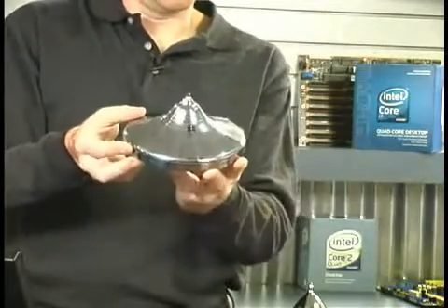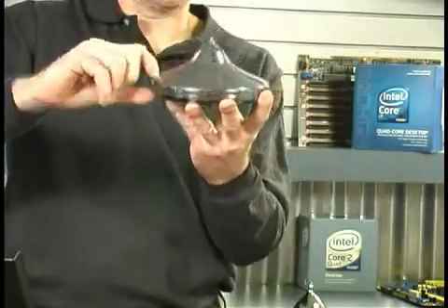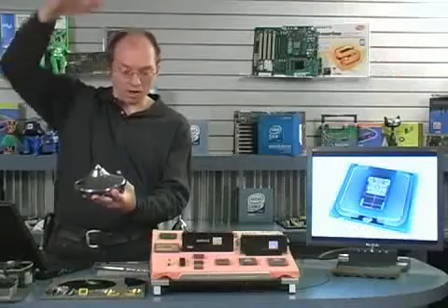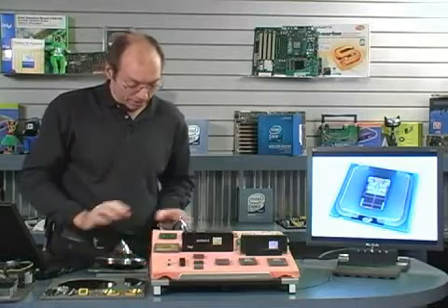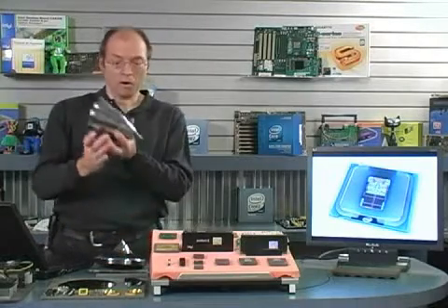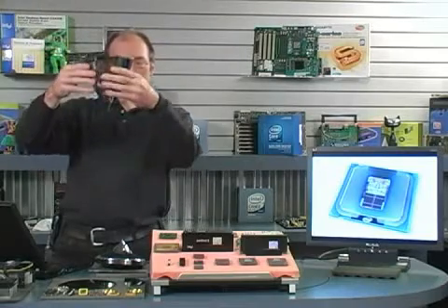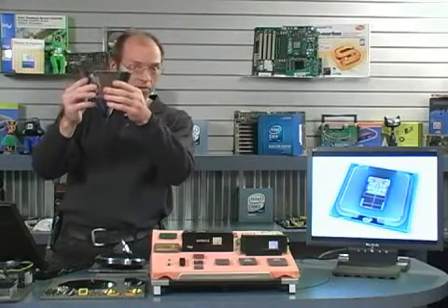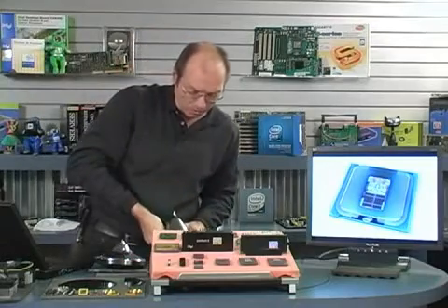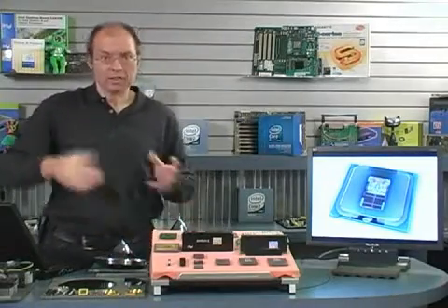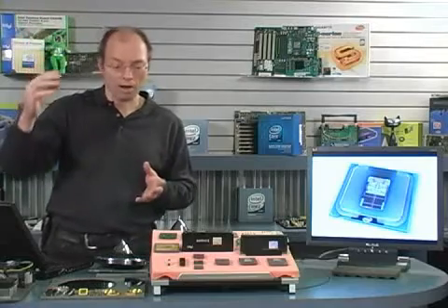In fact, this was an aborted crystal process. Normally, the main body would be not just an inch here, but would be several feet tall. This, in fact, is here as an example of a tail of a more complete crystal. So if you can imagine, this thing was several feet tall, and then this was the tail that's basically cut off and is considered waste. The head and the tail are then chopped off of this crystal. So now what we have is this cylindrical crystal of silicon. Head and tail are cut off.